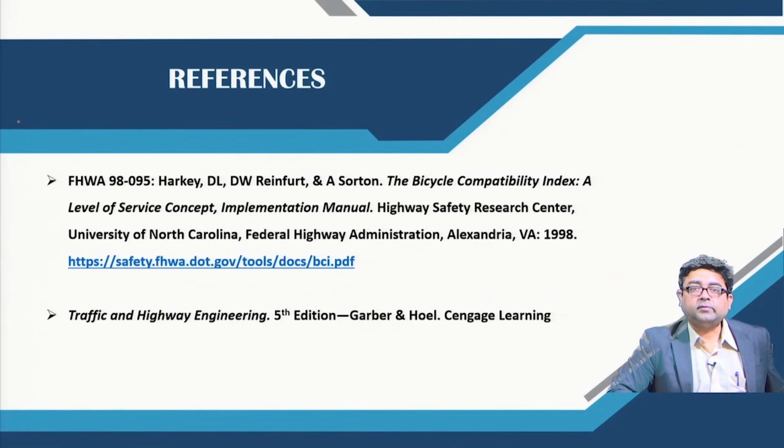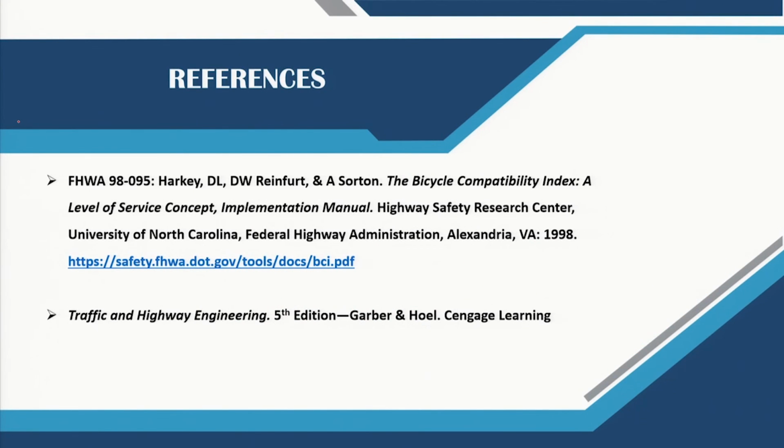So, that is how you have to use your bicycle level of service. Hopefully, you now have an overview and understanding of how bicycle level of service and compatibility index can be calculated. As we have already told you, this is a very new phenomenon in India, and we are yet to develop our own measures, but giving you an idea about the international best practices helps you take it forward and develop an India specific bicycle level of service.